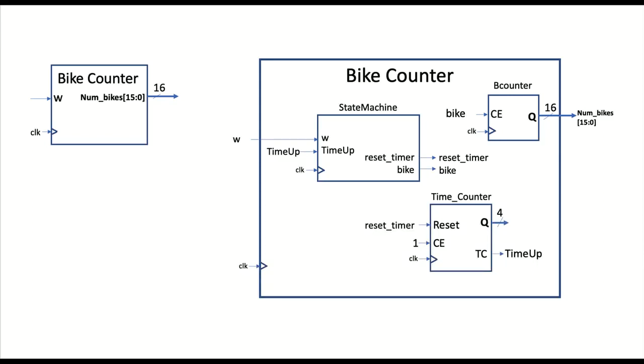Now, the bad thing is, if you forget to hook up your outputs, say you don't put any outputs in your top level, your whole design will get removed. And I've seen that happen.